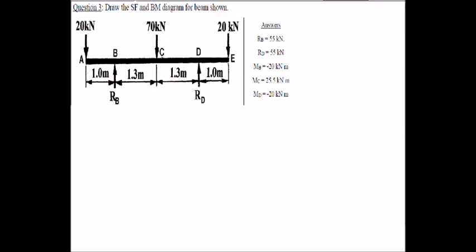Question 3. It's actually a symmetrical beam here. Now, an engineer likes symmetry because symmetry helps them with the analysis. Because the beam is symmetrically positioned, so the supports, the RB and the RD, the reactions are symmetrical, and the loading is symmetrical here when we look at it, we can actually write down by inspection the reactions.